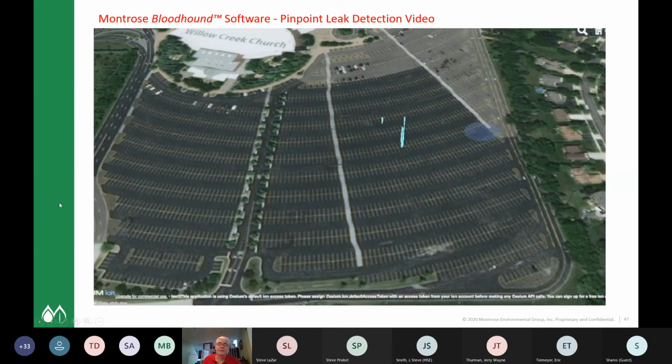So we use this out in the field to find some leaks and do a little bit of monitoring, and help out if you have some blown Summa cans on a fence line, or some Method 325 benzene tubes that are out. We can take this system in, usually within a day or two of fence line mapping, depending on how big the facility is. We can plot out where most of the leaks are and where most of the sources of those are.